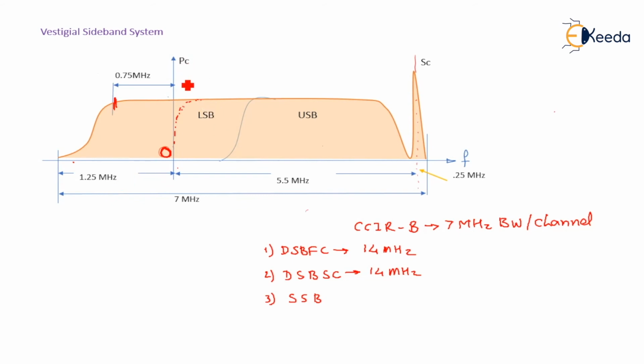as the picture and the sound carrier both are placed at 5.5 megahertz away from each other to avoid the interference between them. Here after the sound carrier, again 0.25 megahertz band separation is provided.